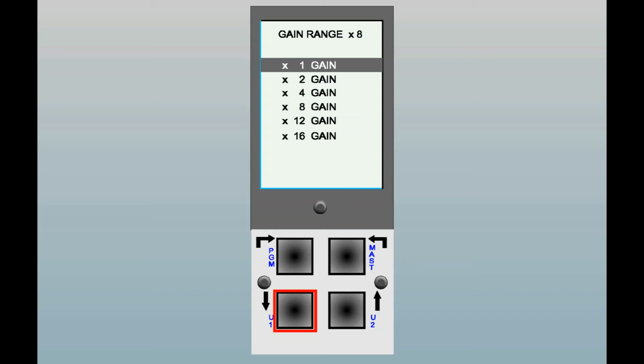Determining which gain setting to use is generally a matter of trial and error, as it will vary with the gauging fixture design. For a new setup, we generally recommend starting with an 8 times setting. If manual mastering shows that there is insufficient range with the min and max masters, then the mode gain can be increased to a higher value. And if the range is too great, likewise the mode gain can be decreased. This affords the maximum flexibility for a wide range of fixture designs.